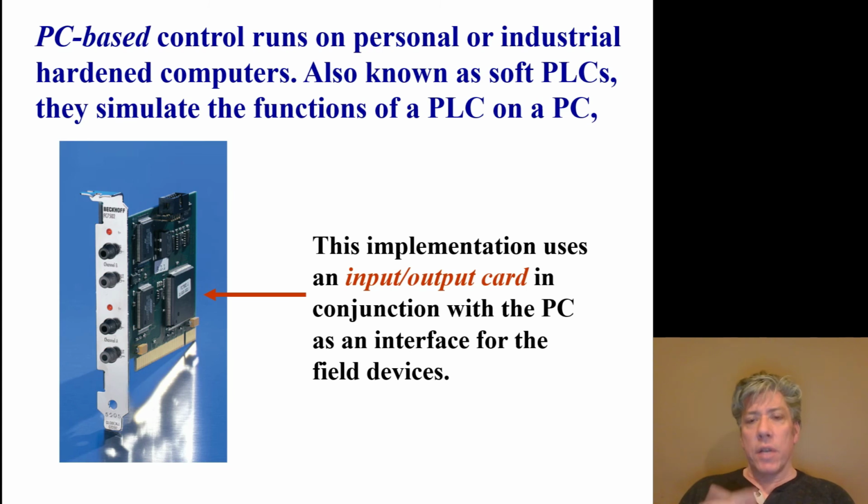One of the other issues with PCs is trying to connect all the I/O, if you don't have distributed I/O. PCs are set up in a standard way where you can see the slot here, the card that plugs into the computer. The height of that tab and the width and everything, that's a standard that's been around for quite a while now. And connecting enough I/O to it is really not practical. So that's one of the other limitations of using PC-based controls.